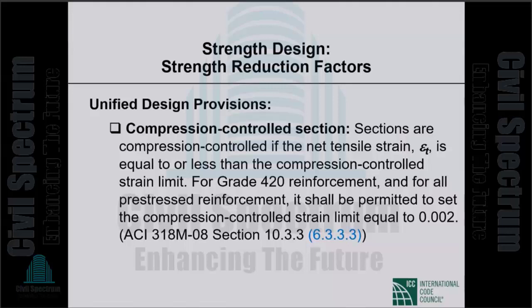Sections are compression controlled if the net tensile strain as defined is equal to or less than the compression controlled strain limit.